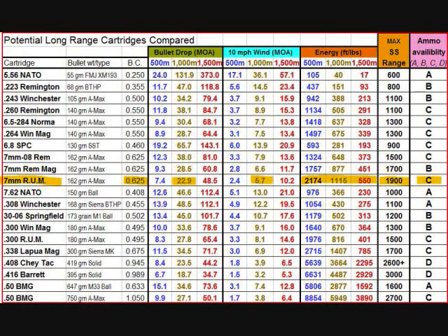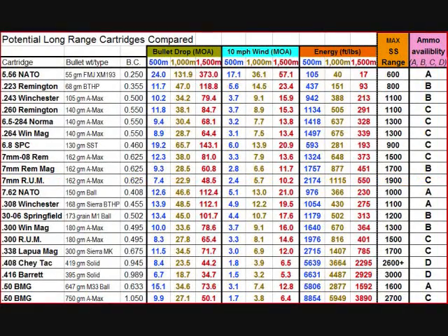One trade-off you're going to have with the Ultra Mags, and you can read about this more when you're looking at your particular caliber choices, is they do have quite a bit shorter barrel life because of throat erosion. You got so much powder smoking through that little hole with that big case and that smaller diameter bore. It's kind of hard on your barrels. So a 300 Winchester Magnum actually might be desirable if you're going to shoot this thing a lot because it's not so overbore as a 7mm Remington Ultra Magnum. But your 300 Remington Ultra Magnum doesn't have the same problem as the 7mm Remington Ultra Magnum. So actually the 300 RUM is really good as well.